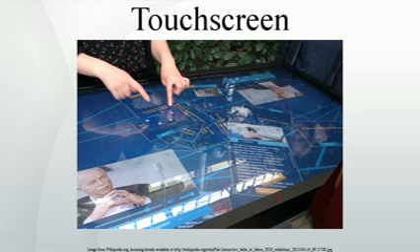Since there is no need for additional elements on screen, it also claims to provide excellent optical clarity. Also, since mechanical vibrations are used to detect a touch event, any object can be used to generate these events, including fingers and stylus. A downside is that after the initial touch the system cannot detect a motionless finger.